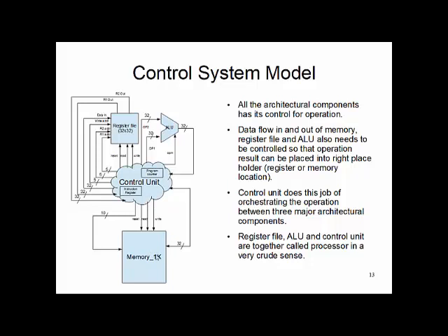And then in the next cycle, the memory returns the instruction to the controller, and that instruction is stored in the instruction register. Okay, so this is what we call the instruction fetch cycle, where it picks up the next instruction to be executed by the computing system, and that next instruction is pointed to by the program counter, which stores the address of the next instruction in the memory.